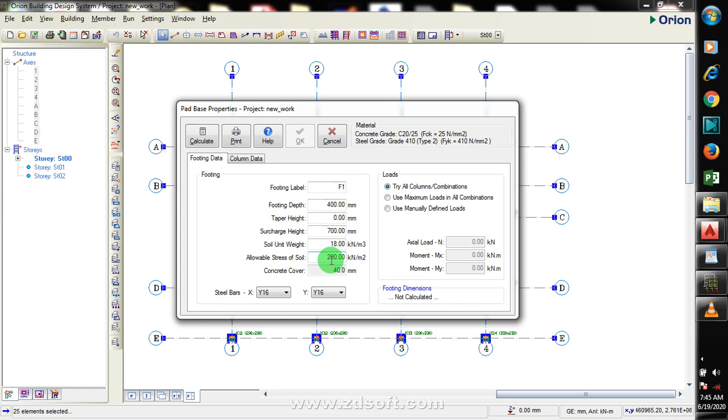But if you find yourself in the north, most especially in Kaduna, that I'm familiar with, Abuja, Niger, Nasarawa, maybe part of Kano and Katsina, where you have good soil bearing capacity, most of the areas in Kaduna are around the range of 150 to 200, sorry. They are always within that range. That's why you see most buildings around here are being done with pad foundations. But in the case of Lagos, mostly around the water area, those soils which are very bad use mostly raft, and sometimes you use pile foundations in those areas.